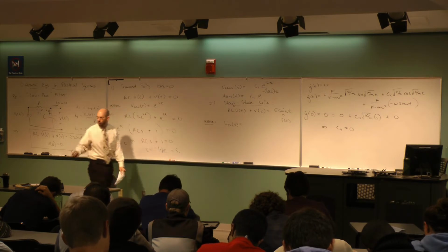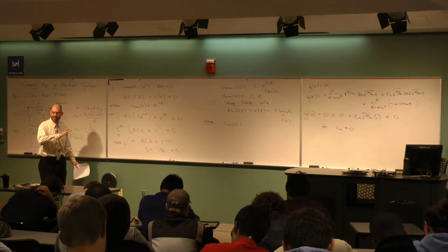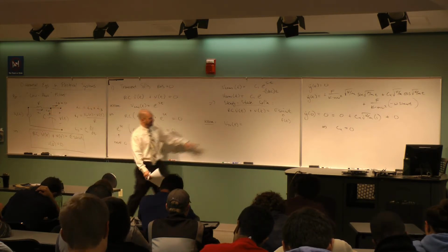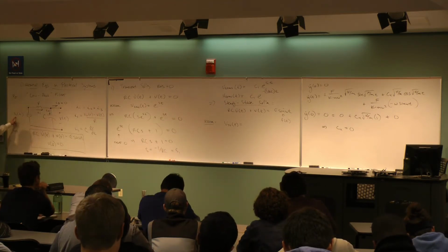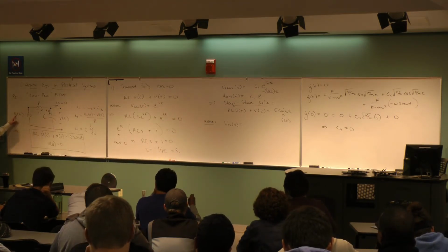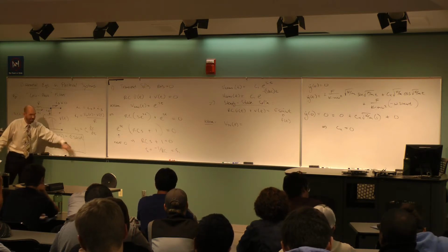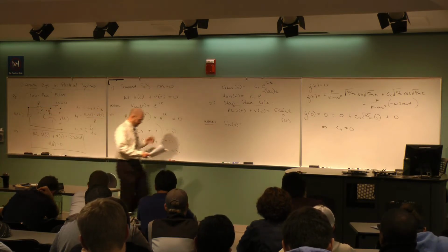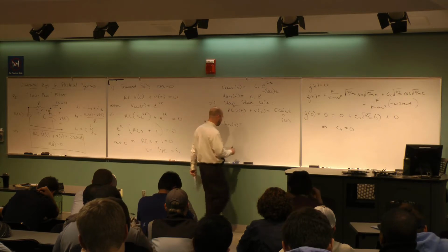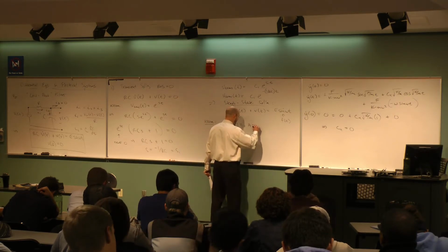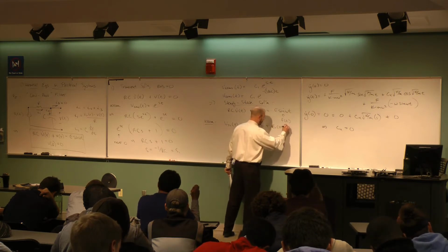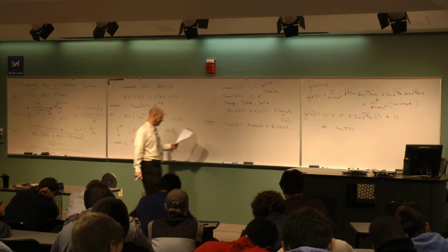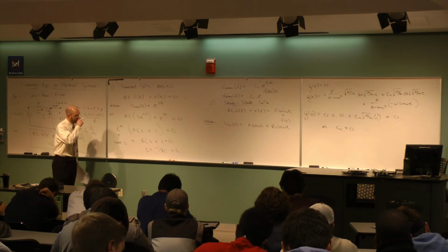Okay, and again, when you solve these differential equations, be really anal with your notation. V steady state, there's 2 s's. I already have a v with 1 s over here, okay, which was this guy here. All right, be careful not to duplicate notation and get confused. So what am I going to use? Sines and cosines, I'll use a times the sine omega t plus b times the cosine omega t. Right? Any combination of sines and cosines could work.